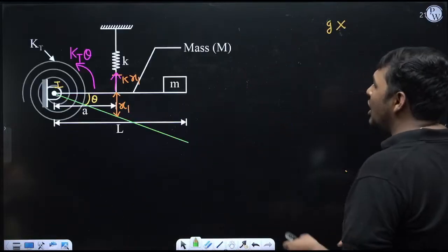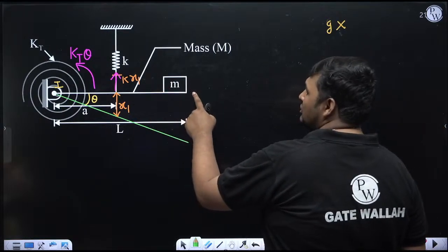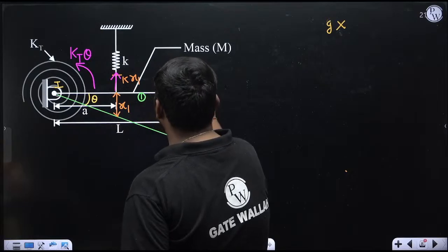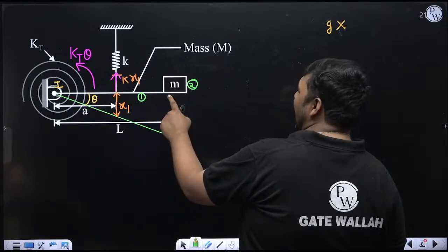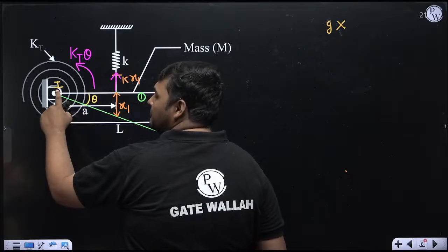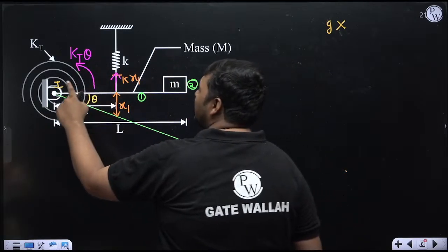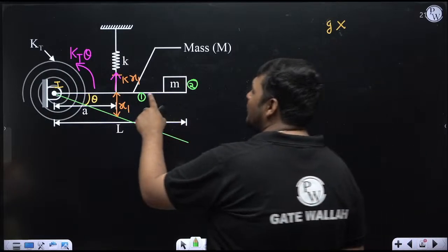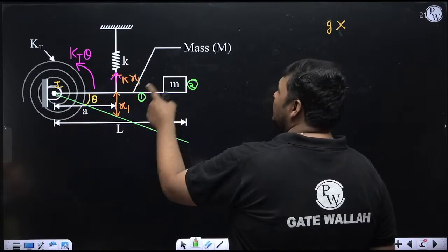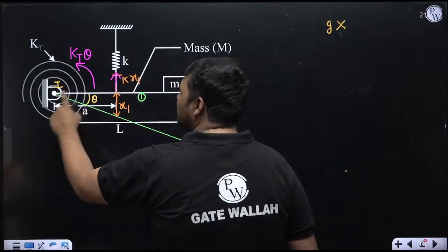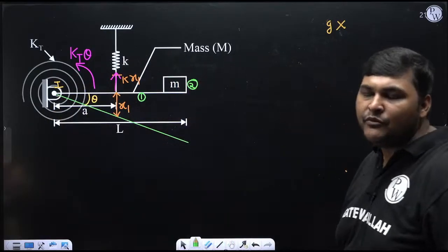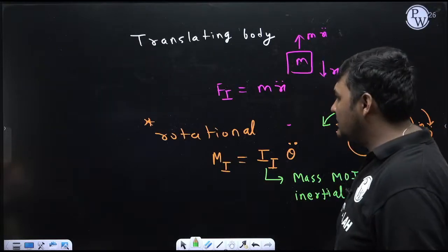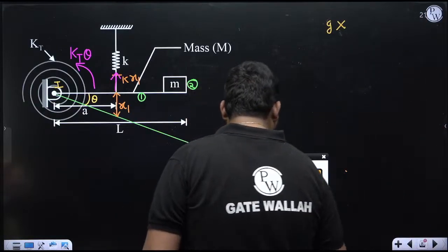So right now the inertia of the rod is given and the inertia of the point mass is also given. But can I say there are two types of inertial bodies here? Suppose this is body 1, this is body 2. But can I say the I center of both bodies is this point I? So first calculate the mass moment of inertia of both bodies about this point. First I am calculating the mass inertia of body 1 about this point, that is the rod. Then I am calculating the mass inertia of the point mass about this point. Then add them, and we will get the total mass inertia about I center, because for the moment of inertia we require I about I. Yes. Now for this question I will calculate, but see,